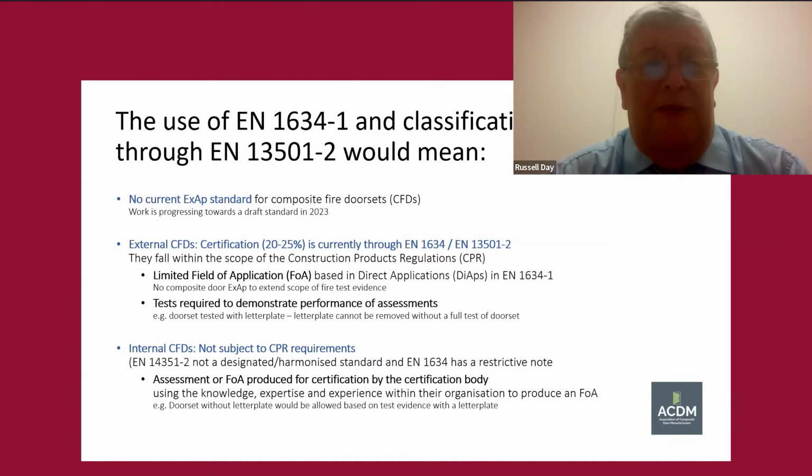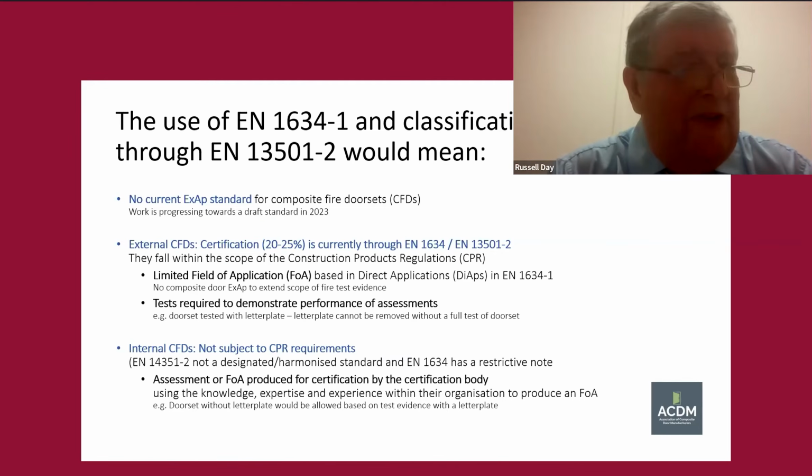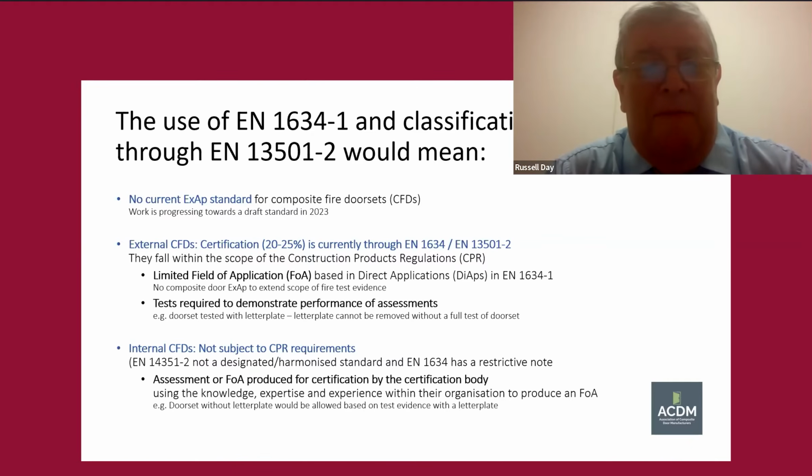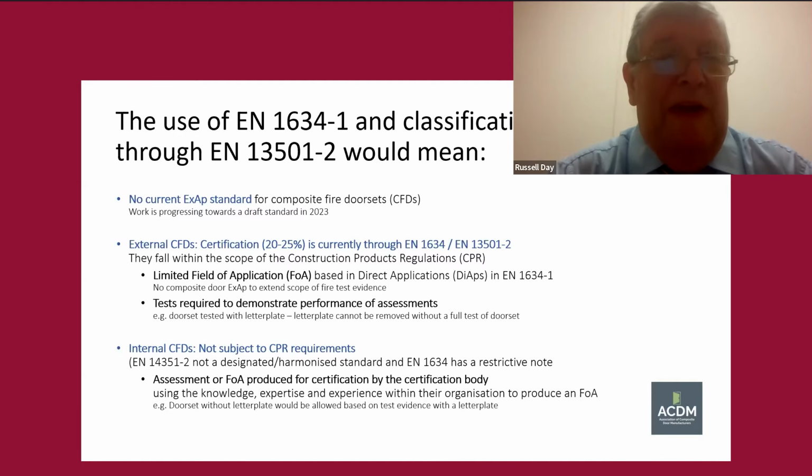So if we do go down the route of 1634 testing and EN 13501 Part 2 classification for composite fire doors, because we don't have that extended application yet, the only extension of scope within the testing would be from the direct applications within EN 1634 Part 1. So it becomes very limiting. A typical example was that one of our members had a full scope written for their external fire doors.